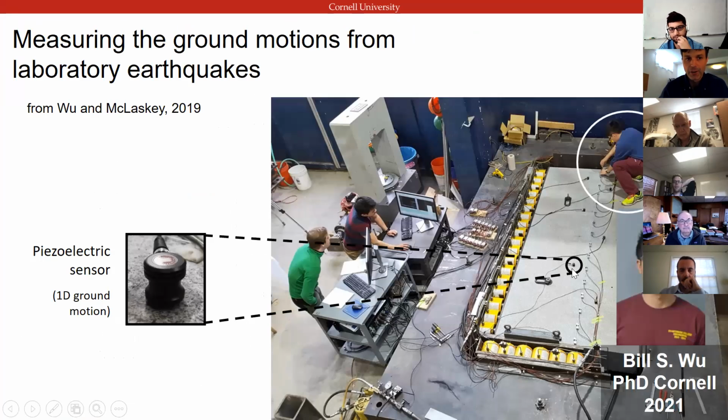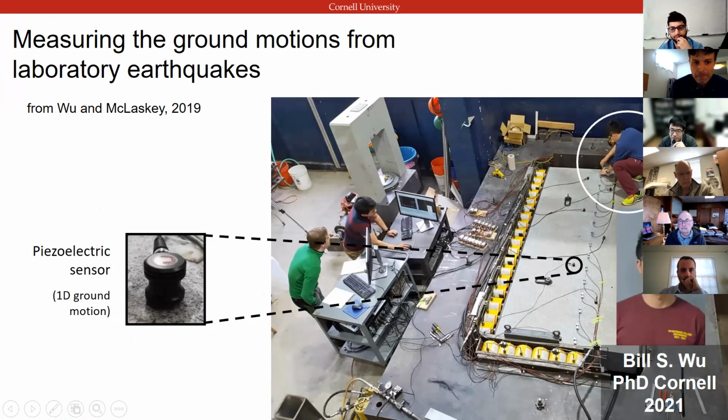What about further increasing the normal stress? It's pretty limited currently. Is it an economical reason, or is it technical? I designed this machine to go up to 20, 25 MPa. You can't go much higher than that before the fact that you're only biaxial starts to be a big problem, right? We're not confining the sample up and down. So if you go much higher than 25 MPa, you'll start to get the rocks falling, and so you'll ruin your sample.